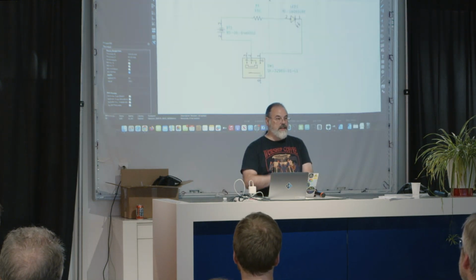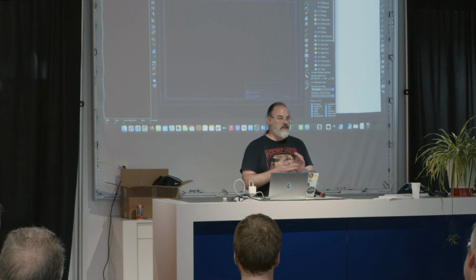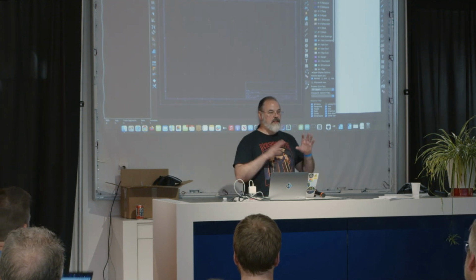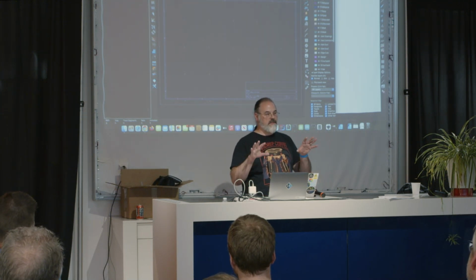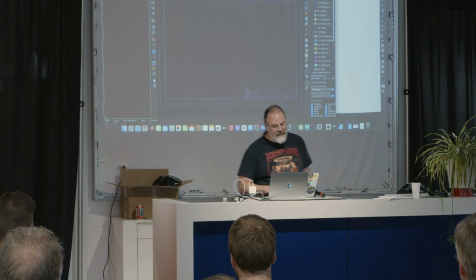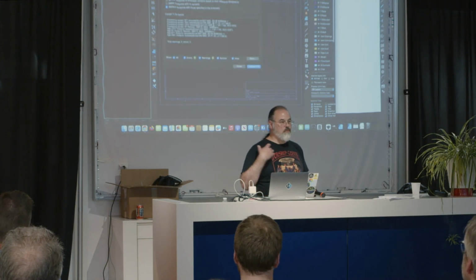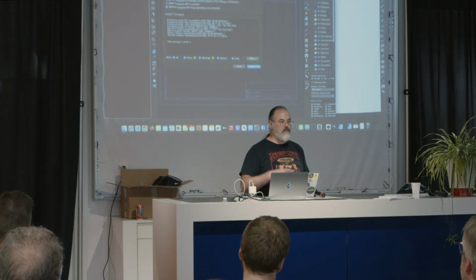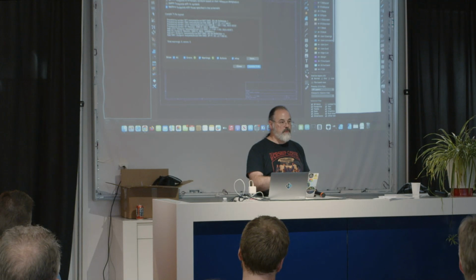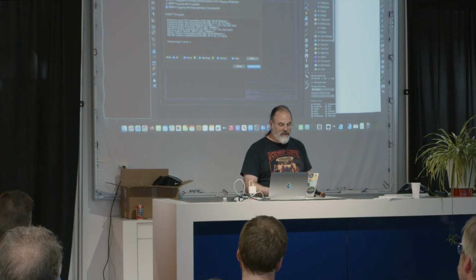Now with all that dialed in, I'm going to switch over to the PCB, and I'm going to hit this update button. Unlike in Eagle, where you have to have the schematic and the PCB open at the same time or things start to go crazy really quick, in KiCad you use this button to basically synchronize them, and it gives you way more control over how it's doing it and what it's going to do. It tells you what it's going to do before you do it so that you can change your settings and make sure that you haven't screwed something up horribly.